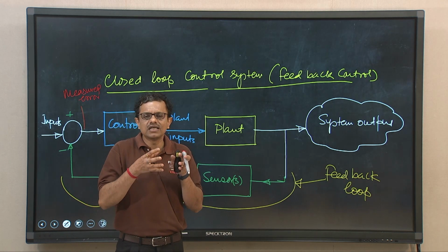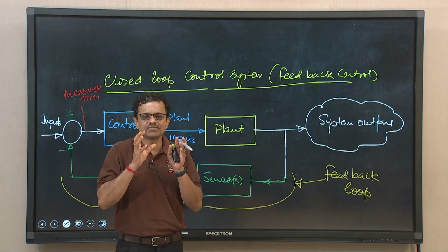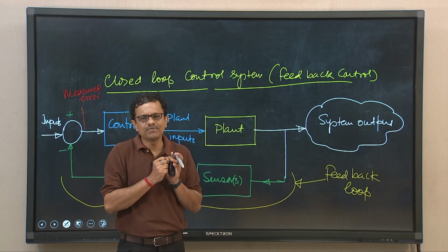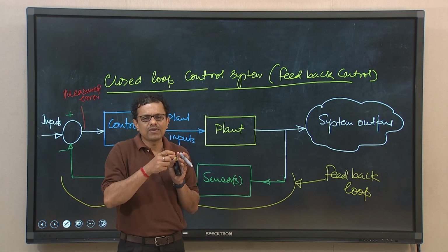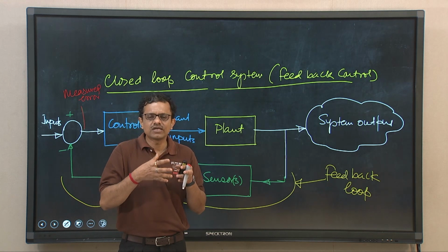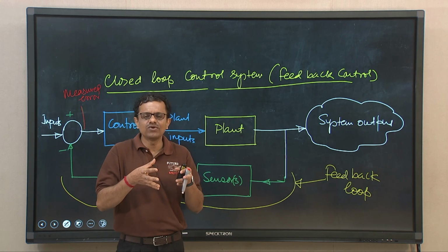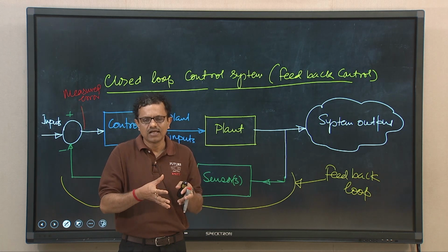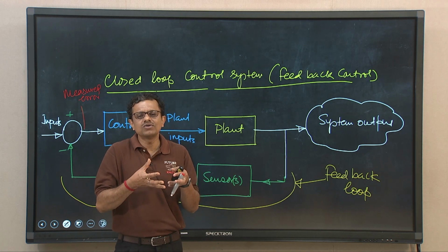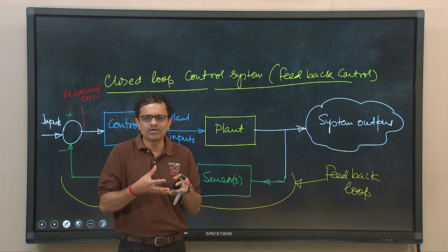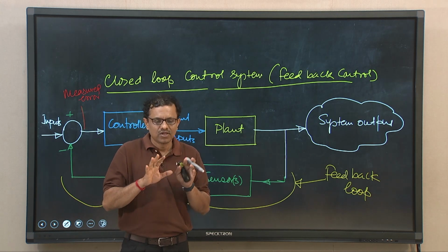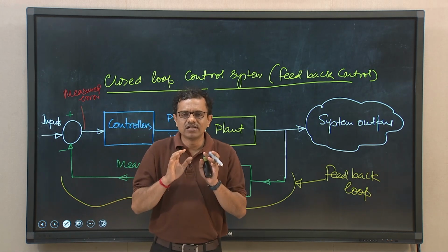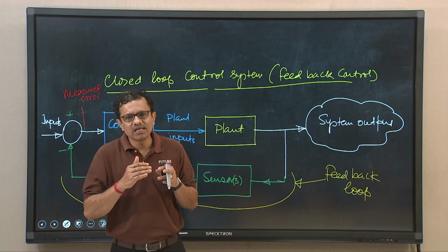So, what will the ECU do again? It will give a signal to the intake manifold or throttle valve to supply more air, so that the excess fuel can combust with the additional air supplied, and hence the oxygen concentration level in the exhaust gases will be optimum.